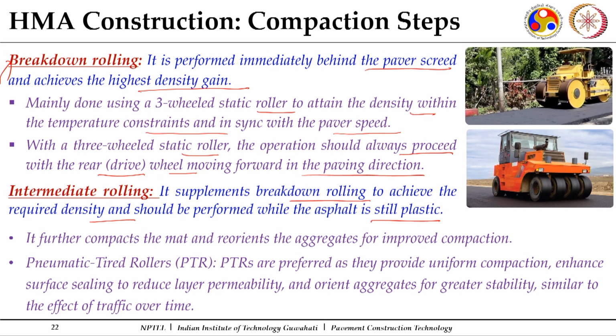So this has to immediately follow your breakdown rolling. Here, most of the time, we prefer to use pneumatic tire rollers, and we call them PTRs.